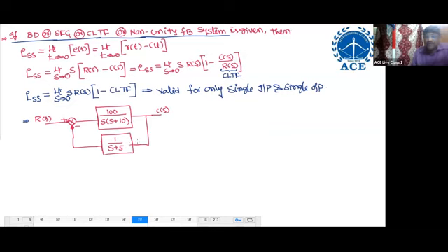That's all. Now find the closed loop transfer function. Substitute here, you will get the answer. C of S by R of S equal to 100 by S into S plus 10, opposite sign of the feedback plus, numerator 100 product with feedback gain 1 by S plus 5.